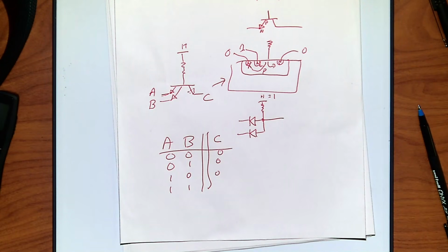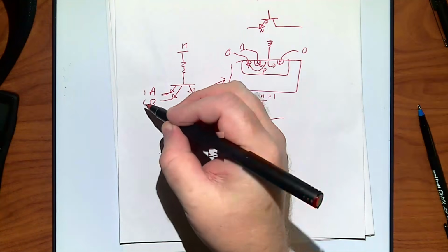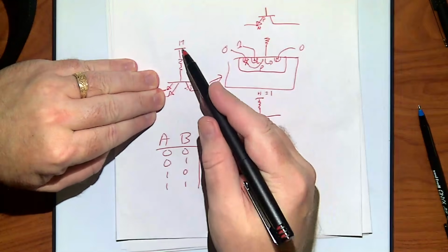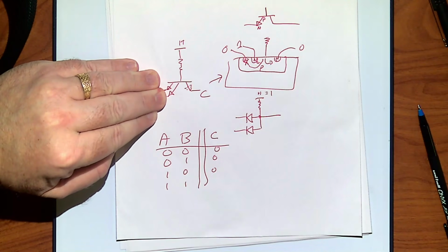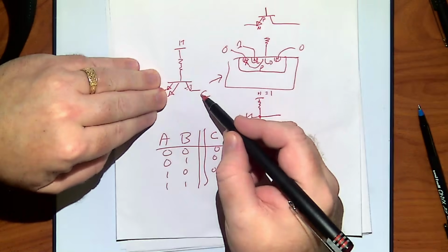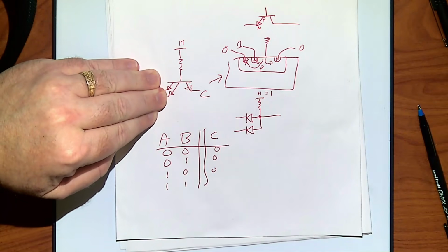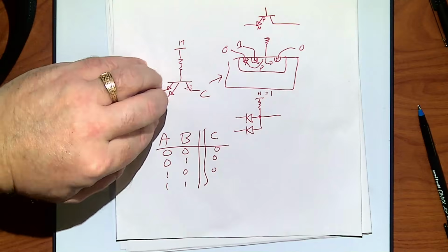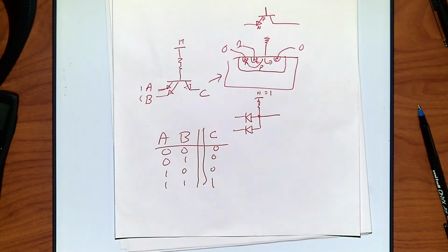Does that make sense? Because if these are both ones, they're in essence not doing anything. So this is just a diode, and that's once it's already mostly in forward bias. So this one cannot be less than high minus 0.7. Otherwise, that diode opens up and flows. Okay. So then, therefore, this becomes a 1.